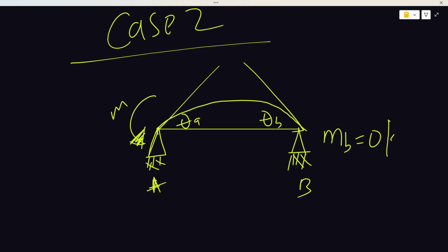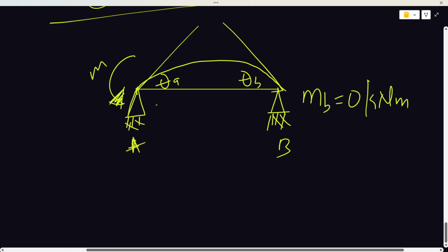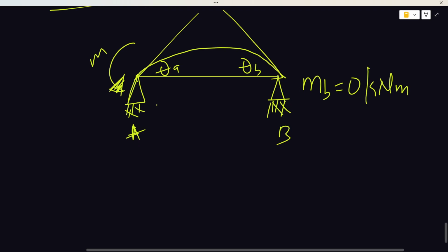This is normal analysis. We all know this. So, if this is the case, we can still invoke the slope deflection method, eliminating theta B. When I mean eliminating theta B, I mean making theta B the subject of the formula and substituting it in the formula for MAB, which is basically M. So let's do just that, and you see.